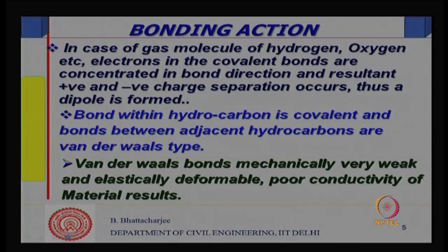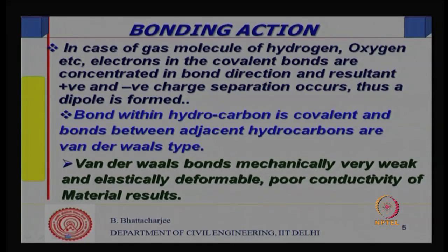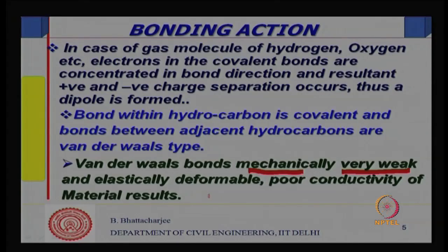So, CSH gel has this sort of bond, which is not a strong chemical bond, but a van der Waals kind of bond, and gel to gel separation requires breaking those van der Waals bonds, right. Many other materials do not have any bond at all. For example, sand particles: between sand particles there are no forces of attraction holding them together, or stones, because of the small surface area per unit mass or per unit volume, the forces do not act, right.